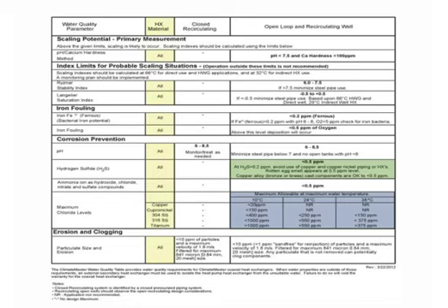There's a couple of them I want to bring to your attention here, and I highlighted them over to the right. That is hydrogen sulfide. If it's a very minor amount, we're telling you can probably use it. If it's too much, well, you're going to want to separate that out from our heat pump or any other manufacturer's heat pump with a separate external heat exchanger. We're going to cover that in a moment. You want to be very careful because frequently hydrogen sulfide will start to attack copper and bronze fittings. So you want to be very careful about the materials you use so you don't install a problem that's going to show up here in short order.